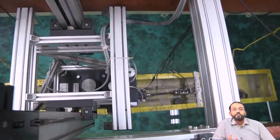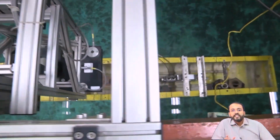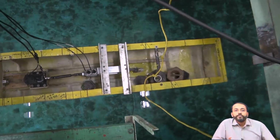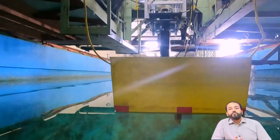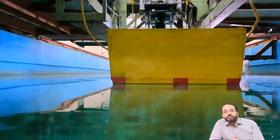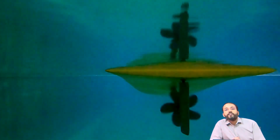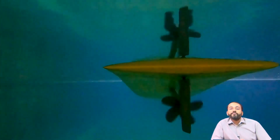This is the self propulsion test condition, where we have the motor and the dynamometer which is connected to the propeller shaft, and we have the propeller which is behind the ship rotating here, and the rudder behind the propeller.